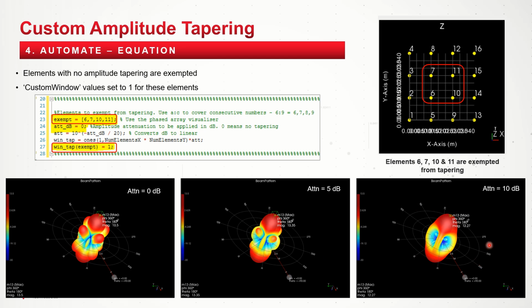And of course, this is the result for 10 dB. So when the attenuator is set to 10 dB, see the result, all the side lobes have been compressed, and of course we lost a bit of power at the center right there.